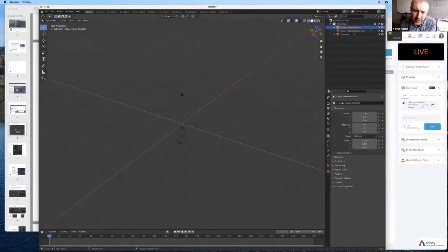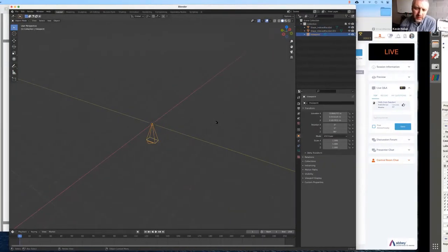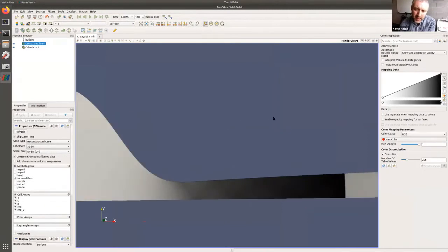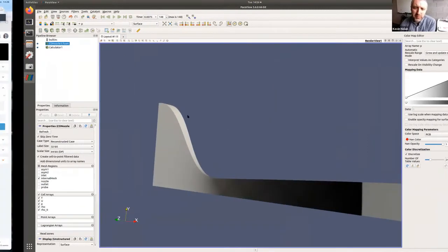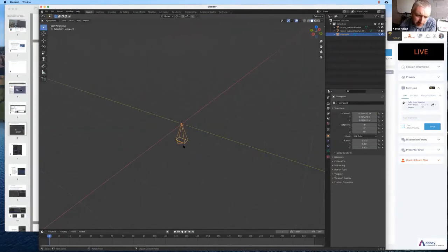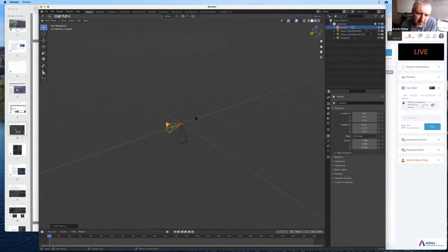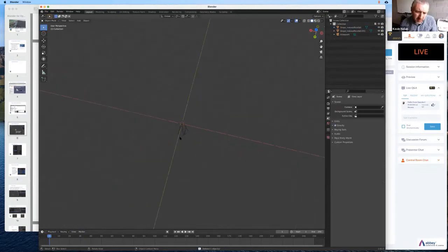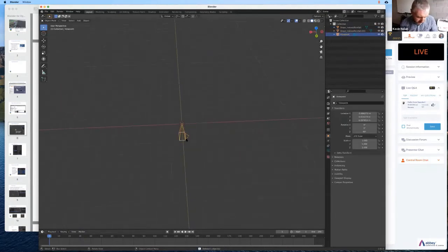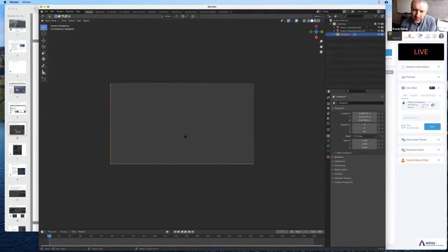And our viewport is then our camera. As you can see, I moved the camera back to this position, and that's remembered. If I had the camera at a different angle, the camera would have that angle too. Now you might have noticed from our previous camera, this little triangle on top is no longer filled. This camera is not active. If I go to Add, Camera, or just Shift A, I can add a camera. This camera is different. It has a little filled-in triangle, so this is the active camera. This one isn't, so I'm going to delete it for a second. The shortcut is just Control 0, or Command 0. And nothing appears, right?